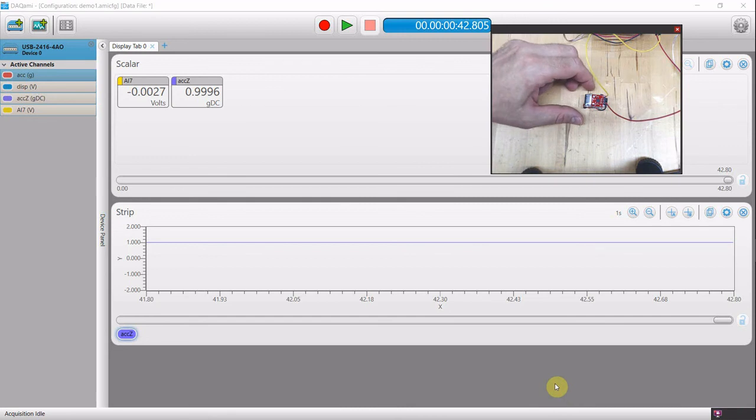After you got your scaling factor, it's a good idea to check if you are correct. The way to do it is to compare the output value in the software from your sensor to the actual value that the sensor sees. Here I have this tiny accelerometer, a very simple one, and I connected only the z-axis. Z-axis is vertical in this direction. The cool thing about this sensor in particular is that it can see constant accelerations. So in this configuration it should show us 1g.